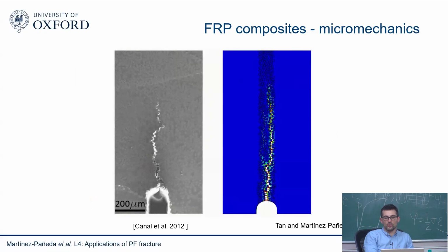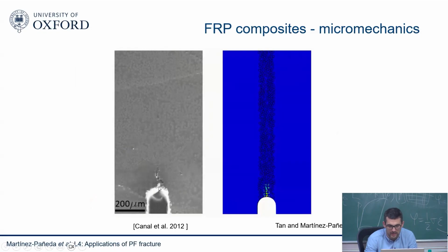So basically, what I'm doing here is I'm telling Abaqus when phase field is larger than 0.99, remove the material. So you see here how the crack grows. You see multiple things happening. You see that more or less the experiment and the model are in relatively good agreement. So they're supposed to run at the same time, more or less they reach the same profile.